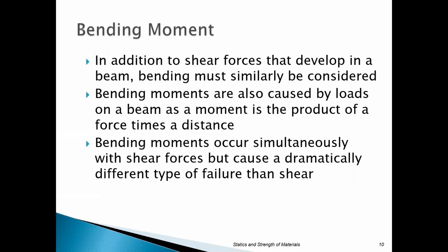All right, so in addition to your shear forces that develop in beams, bending will also be something that has to be considered, because it's going to be something that's going to try to fail that beam as well. So bending moments are caused by loads on a beam as a moment, which is a product, remember, of a force times a distance. So remember, go back to that concept of moment. It's just a force and a perpendicular distance.